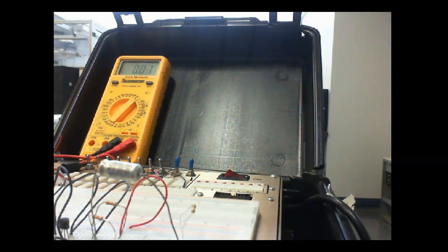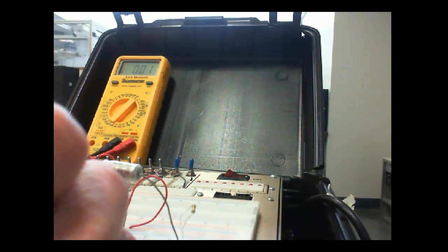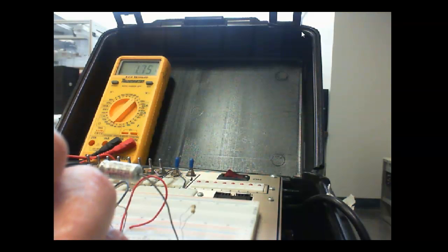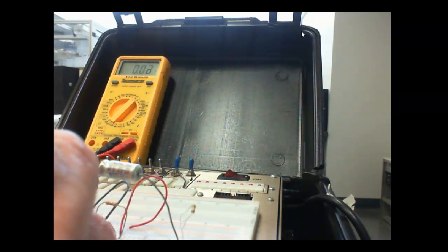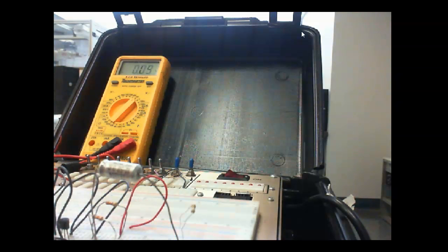Mario says it's going to go up. No, it's not. What was done so far has nothing to do with it. Is R1 still in play? Is R2 still in play? Is RC still in play? Is RE still in play? All those fixed resistors are your bias resistors. So here comes my bias. Here's my base, 1.75 volts. Didn't affect it at all, right? Here's my emitter, 1.1, which is what it was a while ago. So what we've done so far has nothing to do with the bias. So the bias stays the same.